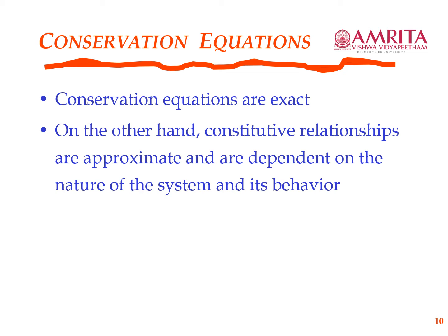So oftentimes these kind of constitutive relationships are obtained from experimental data, and a functional mathematical form is fit to the experimental data. One other example that you can probably recall is how Cp, for example, specific heat capacity, or density or viscosity, all these thermodynamic or transport properties become functions of temperature or functions of pressure, and you express the dependence of specific heat on temperature by some empirical relationship. All those empirical relationships are also constitutive relationships.